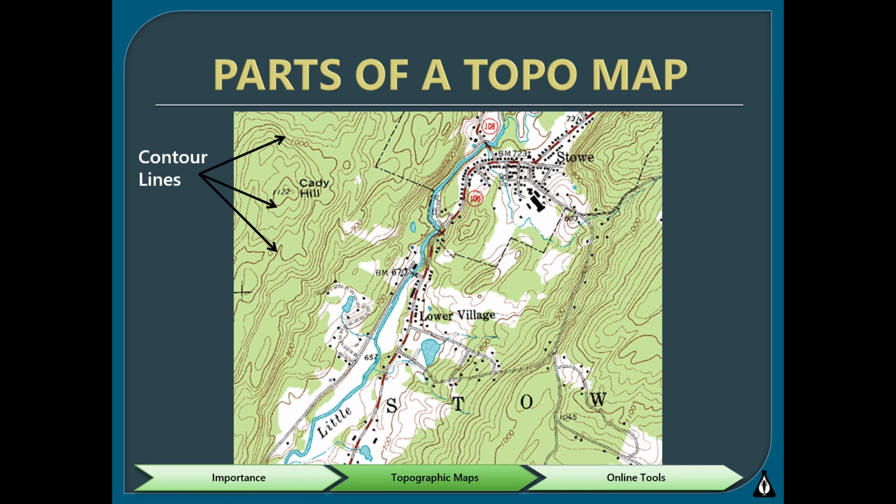The contour lines should never cross each other, and the closer together they are, that represents steeper terrain. So over here, in this area, you can see all these contour lines are closer together, and over here they're closer together, so this shows a steep hillside, maybe even a cliff, whereas these areas over here are showing elevation changes further and further apart, which represents not as steep terrain.